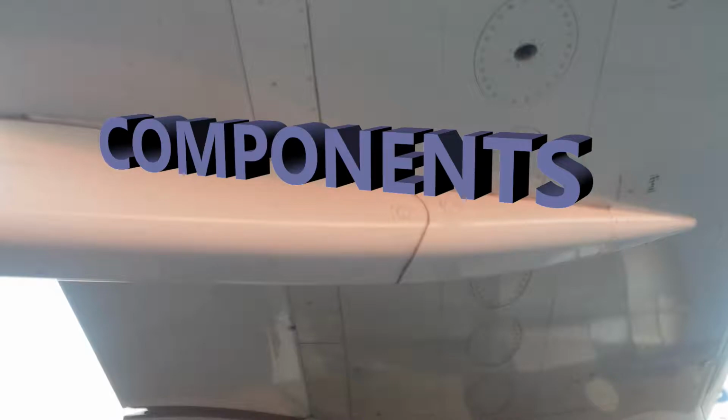All right, so what kind of displays can you have with the fuel quantity? What can you expect on these things? Well, remember I mentioned that you're using fuel density to figure out the fuel mass. So that's going to show up on the ECAM. You see what I mean? So there's a reason why those probes are there. That information is going to be showing up. So the fuel mass is shown on the ECAM as well, with the ECAM SD fuel page.